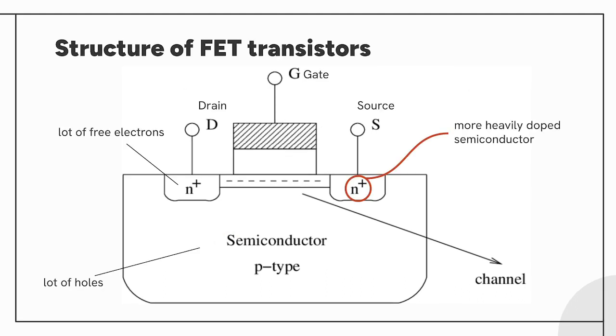If the electrode of the substrate is at 0 voltage and a minus voltage is applied to the gate electrode, first look at the gate electrode: the holes, which are the majority carriers of P-type silicon, are attracted by the minus voltage and the holes gather on one side.